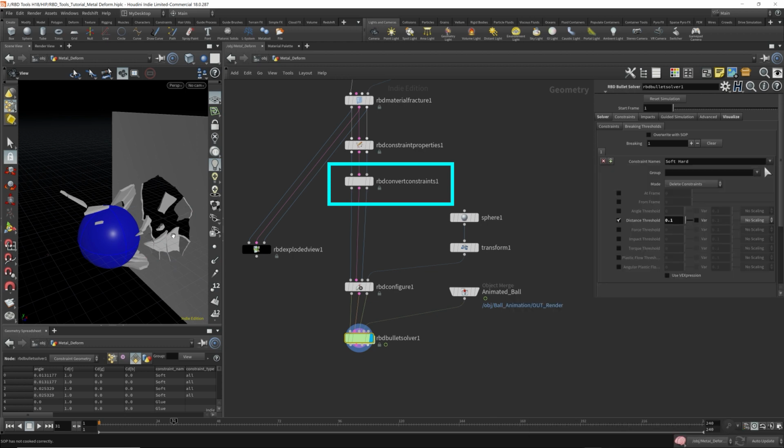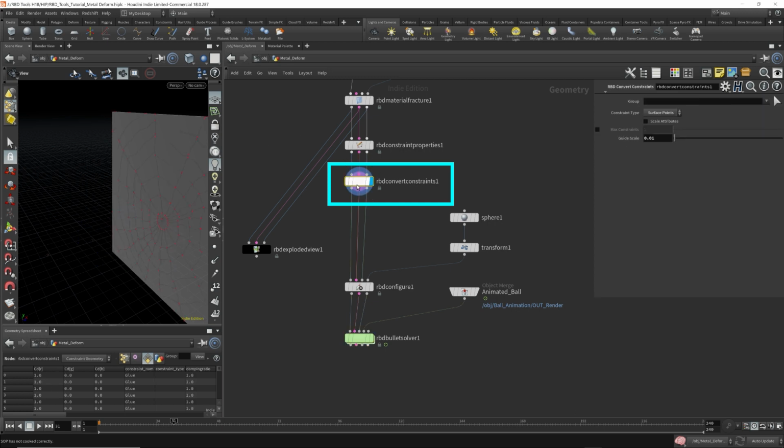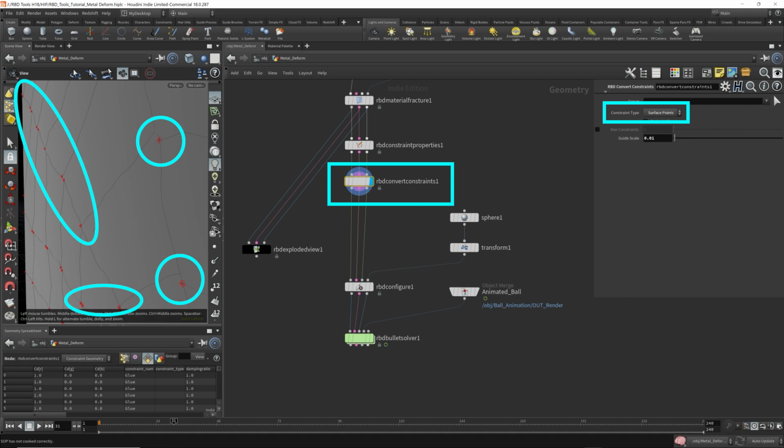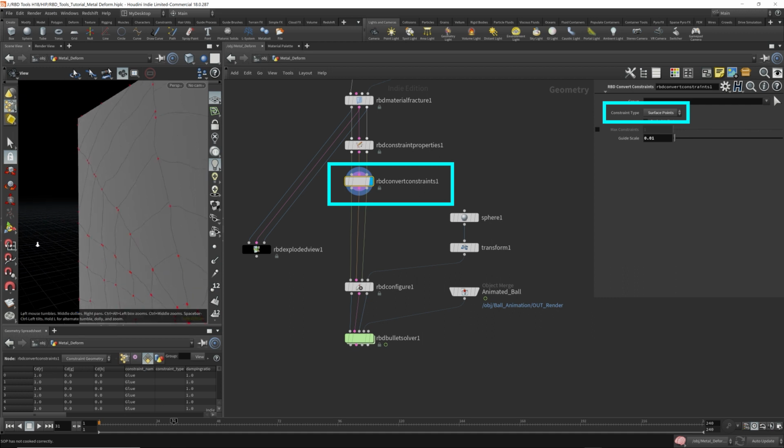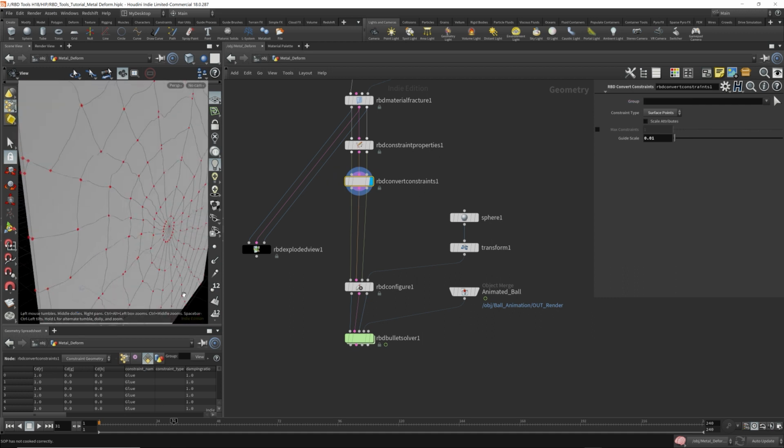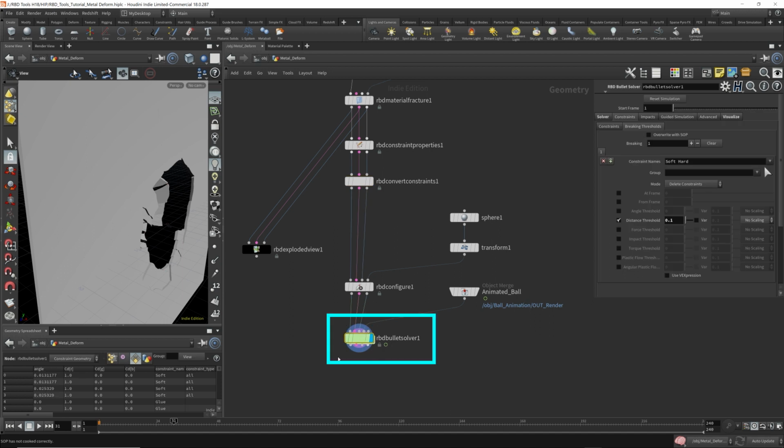And now that we've changed how the constraints are created, the structure of the constraints, we've changed it to the edges. So it's being held, it's being glued together with these points. These are the constraint bonding points. This is where the glue is being placed and no longer at the center of mass. And also, there was another thing that we did too.